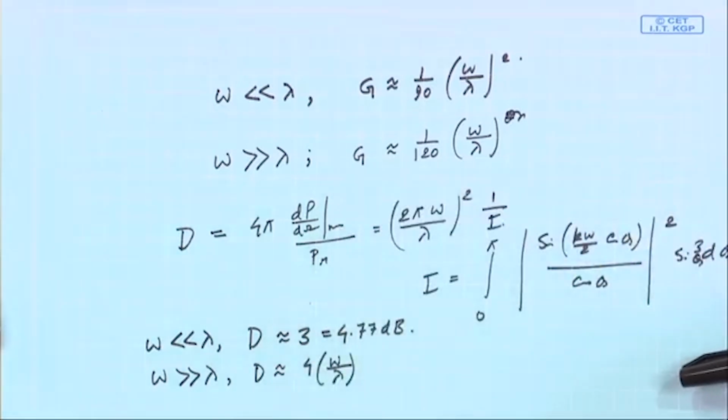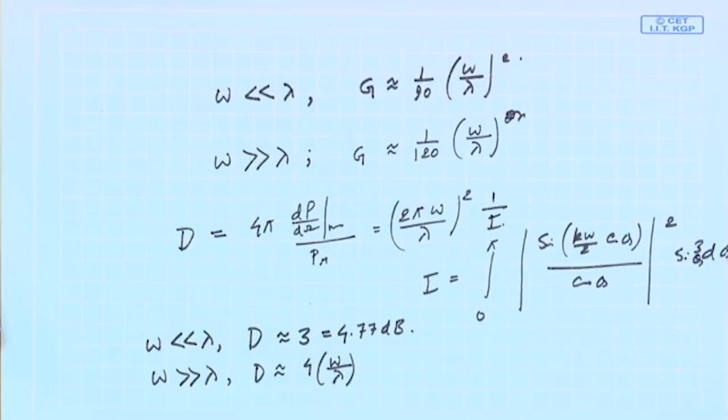conductance is smaller. So, your radiation resistance will be small. So, this is a dichotomy that shows that it is not a good antenna, but where power is sufficiently available, you can use this as an antenna. Also, a major limitation of this microstrip antenna is its narrow frequency bandwidth, because this bandwidth is primarily controlled by the characteristic of the transmission line, the parallel plate structure. So, it is a very small amount.